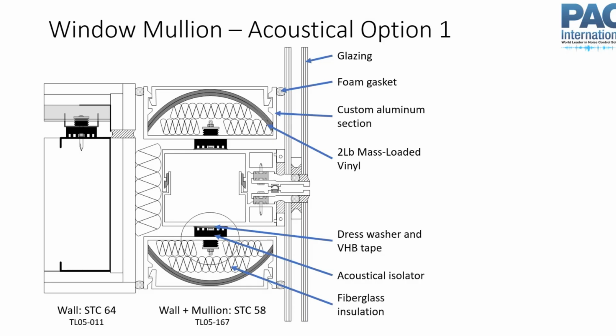Considerations for exterior wall using SIP. Yeah, so SIP is structural insulated panel, so it's OSB with EPS foam insulation in between, a sandwich panel. This is one of those things where I said sometimes what's good for thermal decoupling and isolation is also good for acoustics. SIPs are one where what's good for thermal is not good for acoustics. It's a fairly lightweight and rigid panel, which is great for transmitting sound. We use lightweight, rigid things usually to produce sound, like speaker cones and instruments and things like that.